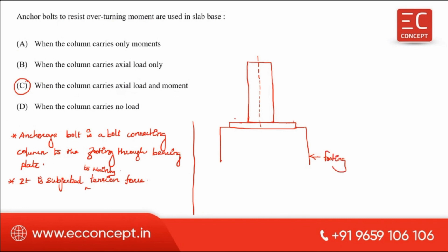And this is the plate, bearing plate. Okay, here the column base plate is connected with the footing by using an anchor bolt. This is the anchor bolt. So generally this anchor bolt is subjected to tensile force.